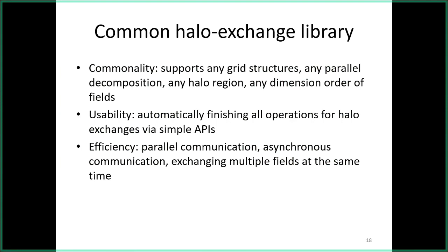It can support any kind of grid structures, such as structured grids or unstructured grids, and can support any kind of parallel decompositions, halo regions, and any dimension order of fields. And it can automatically finish all operations for halo exchange via simple APIs.